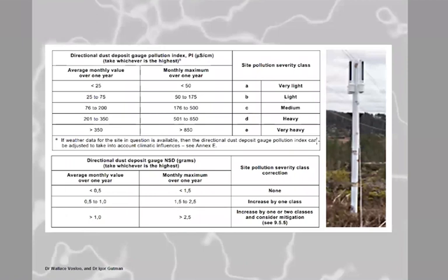We can use dust gauges to get it, directional dust gauges, where we measure the pollution from different directions, capture it into the dust gauge, and then from there we can determine our environmental pollution levels. Very cheap. You're looking at under $300 for a set. When you put on top of that a surface conductivity little device, which is energized every 10 minutes at 600 volts, you measure the current, you get the surface conductivity, and you can get at 10-minute intervals your pollution severity levels. There you're looking at about $2,700 for a device.